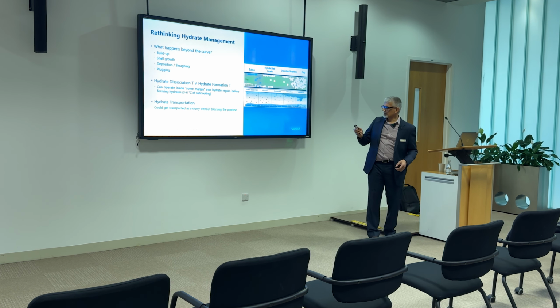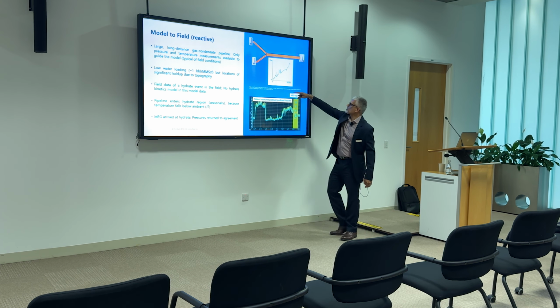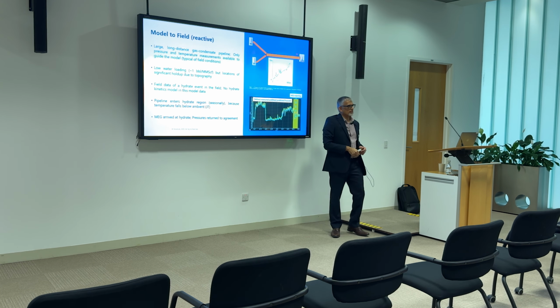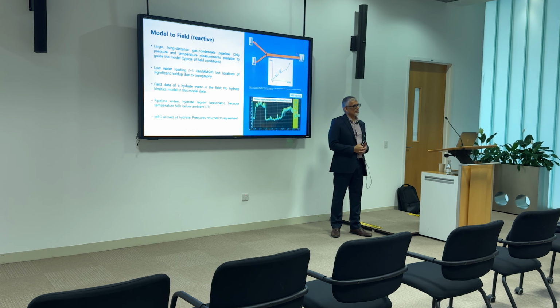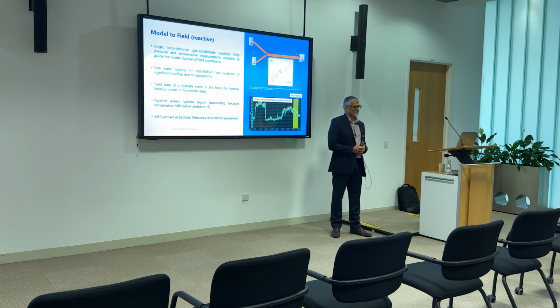So in one of the slides where we had the ups and downs, at all the low points you could get water drop out. So there's a high amount of water, and you get a much higher probability of hydrate formation. Usually, I haven't really come across such an issue in plant.